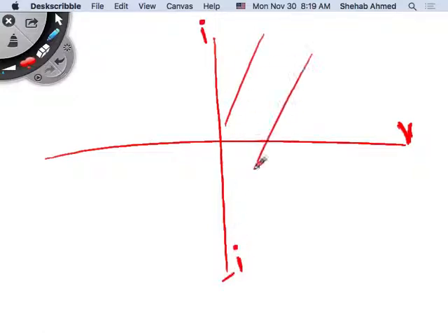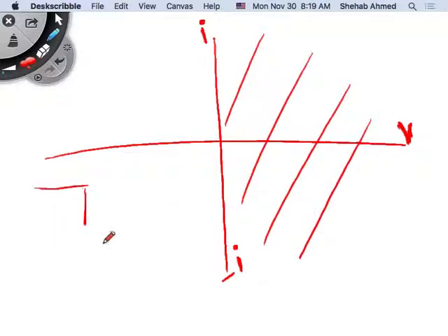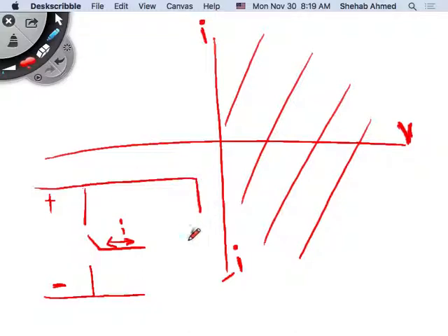So since I have my representation for the single pole double throw configuration here, I have current here that is bidirectional, right? This is my current. Current is bidirectional, and the voltage is unidirectional. This is my inverter, right? This is my full bridge or half bridge inverter representation.